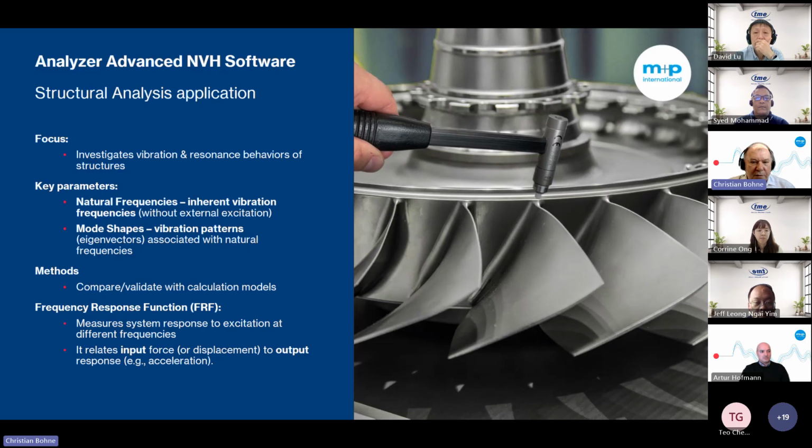And based on that, with the geometry creation, which can also come from a CAD file, like an STL file, for example, we are able to create and to estimate the mode shapes. We want to have mode shapes. We want to know the natural frequency, and we want to know the damping, which goes into FE software.